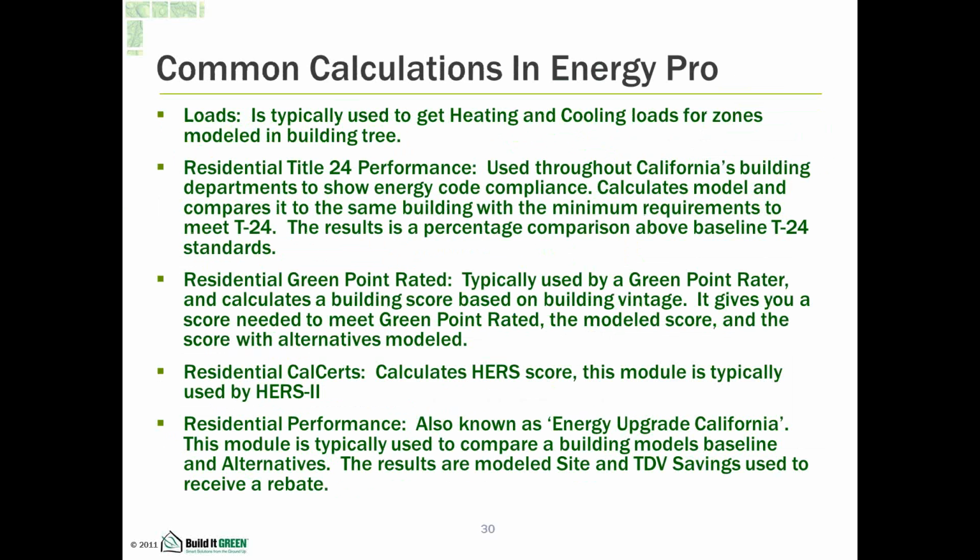Okay, so again, common calculations in Energy Pro. We have loads, which can give you the different loads for the zones or floor levels. Residential Title 24 performance, which many of you already know, will give you a compliance margin based on the proposed and what you have modeled and what's actually code, and if you're actually beating that or not. Green Point Rated is a module that takes your building's vintage and compares it to a building from that vintage with improvements, and gives you a target index to meet.